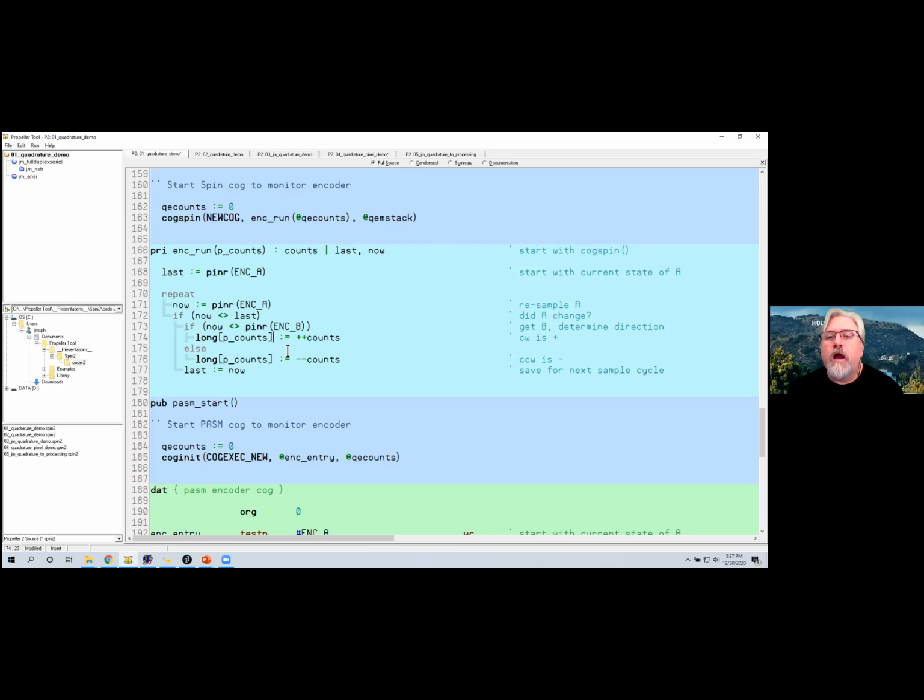Okay. All right. So to your point, Ken, I noticed that because I was playing, far too late last night, but I noticed I was getting a little noise in my encoder. Now, because the encoders we have in our kits are probably mechanical switches. A device like this has optics in it, so we're getting clean outputs, and it's less problematic. So we're not using it in this code, but we could, and that just requires a little extra work. I wanted to keep this code to match our diagrams, keep it very, very simple. But as Chip was saying, instead of looking for just one change, we might want to say, hey, it changed, but it needs to stay changed for a couple of checks so that we know it's really serious about its change. It wasn't just goofing off.